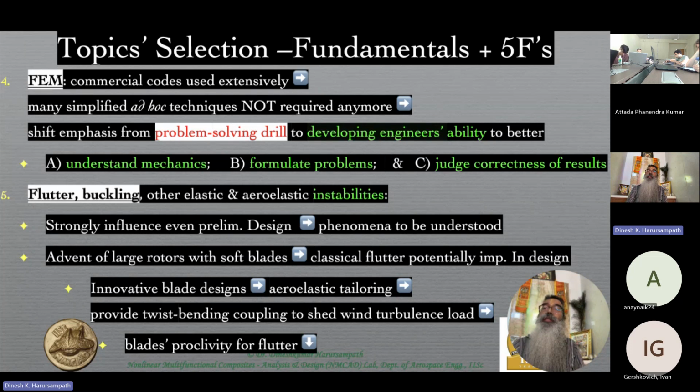In a very generic sense, there are many nuances to buckling, which happens at the global level, which could happen in a flexural sense. In other words, I'm trying to push this, and instead of only contracting, at some point when the compressive load is large enough, this might just bend, kink like this. What is happening is it's a very thin structure like my palm, and therefore its bending stiffness is very low.